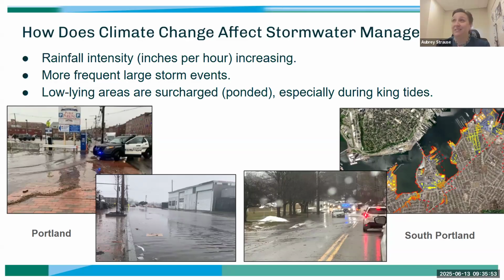So what does this mean to us? Well, you know what? Sometimes this really doesn't mean anything to us. Stormwater, water treatment plants, stormwater systems, they're at the low elevation. They're at the point that water is going to flow to. We can't really move them. They're at the low point. It's going to continue to be the low point, even if sea level increases. So to some extent, we really can't do much about this from a stormwater standpoint at the low point.